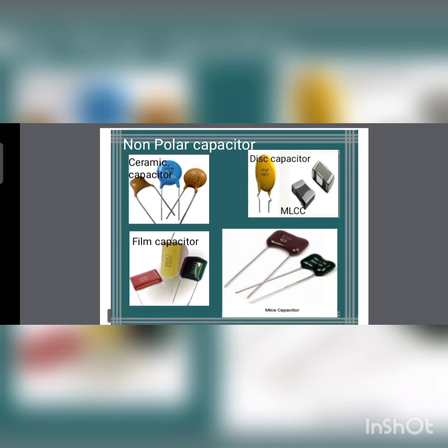Its construction has two types, metallized and film foil construction paper capacitor. In the metallized capacitor, metallized dielectric film is used, which is made by depositing a metal layer over the dielectric film. The metal used can be aluminum or zinc. Film foil capacitor, as the name implies, uses plastic film as a dielectric and is mounted within two layers of aluminum foil electrode. Then mica capacitors are widely used in high frequency electrical appliances and can be used as standard capacitor.